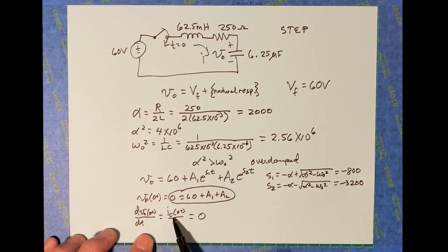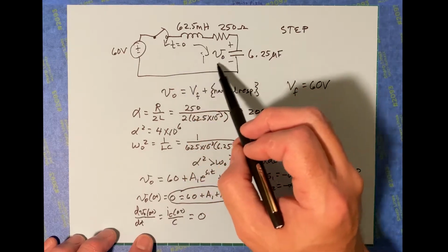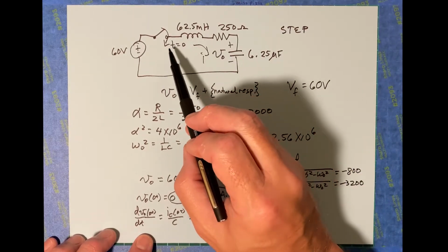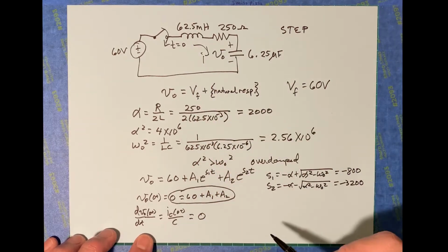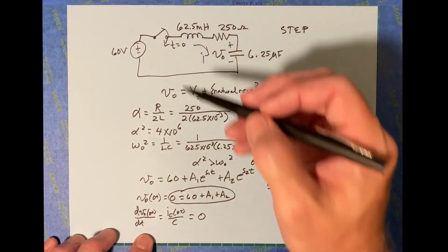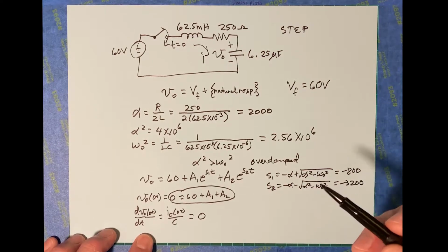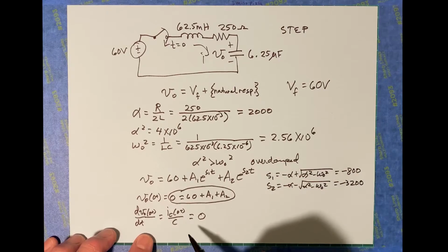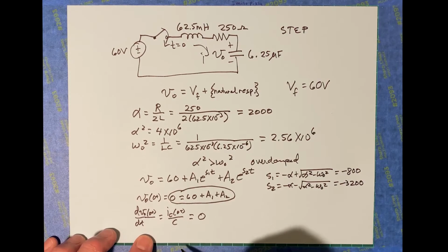Okay, is that the case with the current? Well, initially at t equals 0, remember there's only one current here for all of these elements. At t equals 0, the inductor is going to stop any kind of current flow because it's going to create a back EMF that's going to, at least at 0 plus, not allow current to flow. So yeah, it does make sense that I sub c at 0 plus is going to be 0, therefore this dV dt is going to be 0 as well.